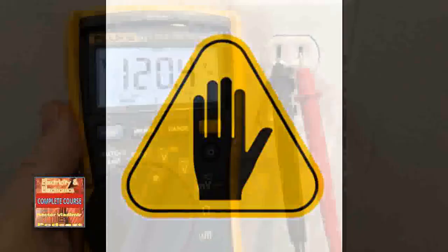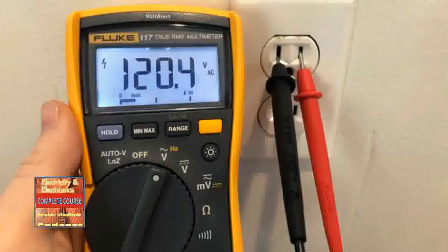Caution. When using a multimeter or a DMM, it is easy to connect the meter to a voltage source immediately after taking resistance or current readings. This is the most common mistake when using a multimeter or DMM. This action will result in damage to the meter or personal injury.